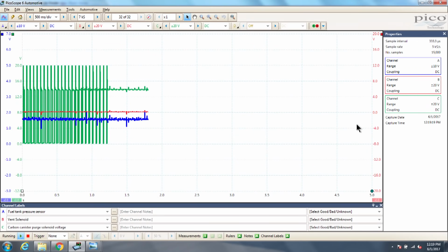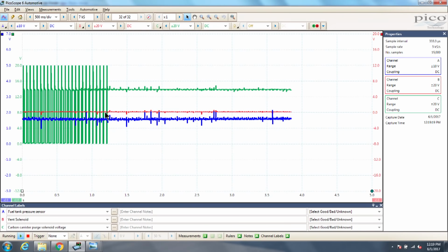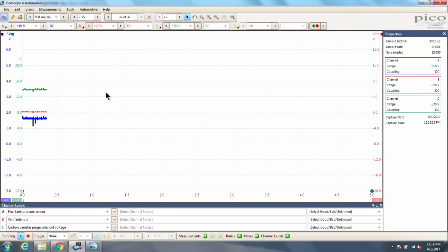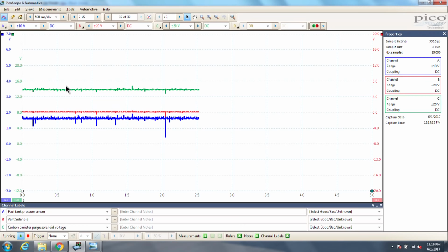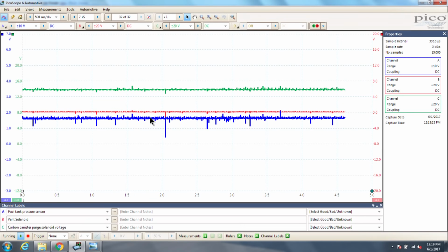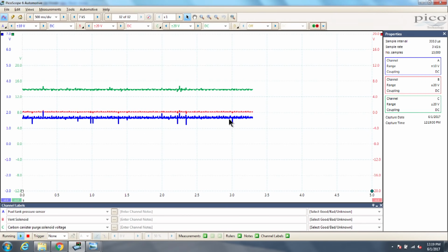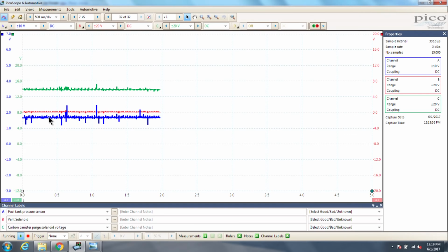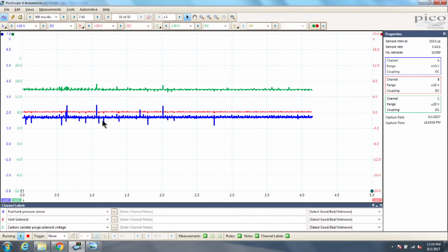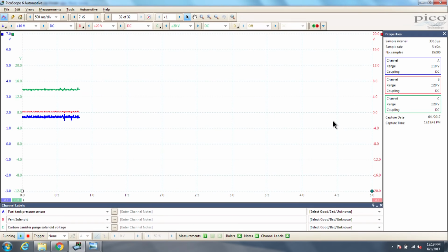Again, do we know what the numbers are? Potentially. Oh, we must have dropped low enough that the computer said, okay, I'm going to shut the purge solenoid off. And now at this point, we would watch the bleed up rate. And slowly, we are bleeding up. Now, it's not happening quickly, and I didn't expect it to because this vehicle does not have a leak, but we are bleeding up very slowly.